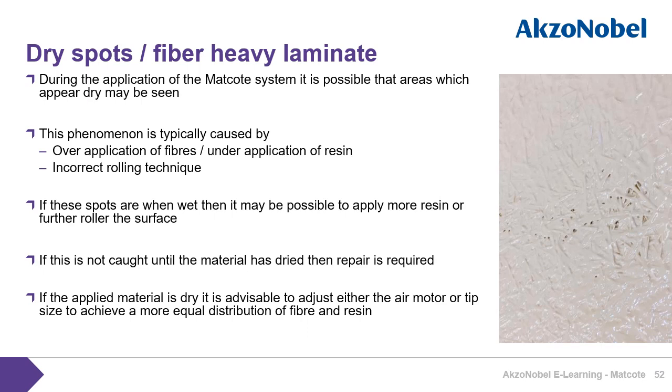If the applied material is dry, it is advisable to adjust either the air motor or tip size to achieve a more equal distribution of fibre and resin.